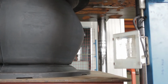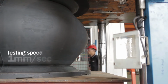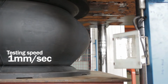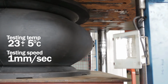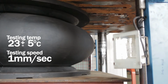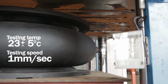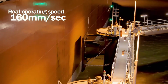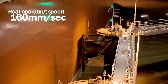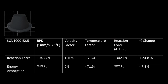Let's look at the impact of temperature factor and velocity factor using the example of an SCN 1000 E2.5 fender. The rated performance data is shown here. In the field, this fender is going to experience a ship berthing of 160 mm per second initial velocity in a location with a temperature range between 10 degrees and 40 degrees centigrade.